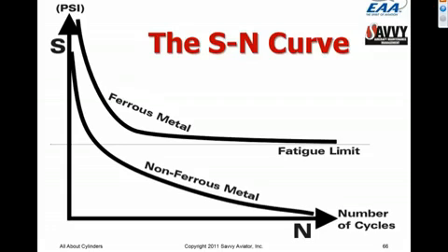But cylinder heads are cycled rapidly and aggressively, and they're made of aluminum, so they're guaranteed to crack after a while. And so we don't want to push it. Like I said, the conventional wisdom is a cylinder head ought to be retired after no more than about 2 TBOs.